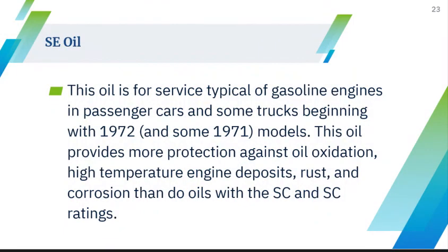Next, we also have the SE oil. It's for service typical of gasoline engines in passenger cars and some trucks beginning in 1972. This oil provides more protection against oil oxidation, high temperature engine deposits, rust, and corrosion, and so do oils with the SC and SD ratings.